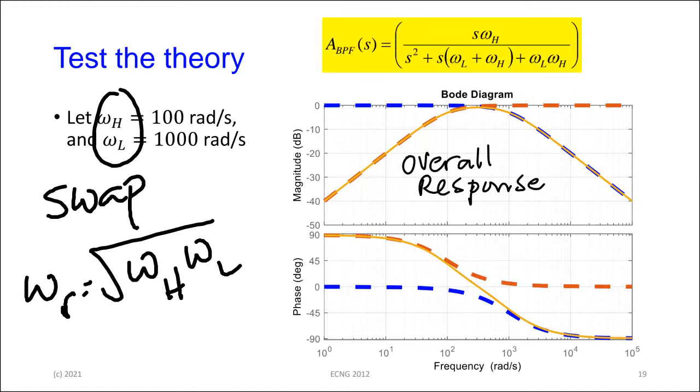So let's go and zoom in on this thing a little bit. Remember the bandpass now is at this point where the phase is starting at 90, passing through 0, and going to minus 90. This here is right where the cutoff frequency is when it passes through 0. And if we zoom in a little bit, you're going to see this is 100, this is 200, this is 300, this is 400. So that point is somewhere between the 300 and 400 mark.